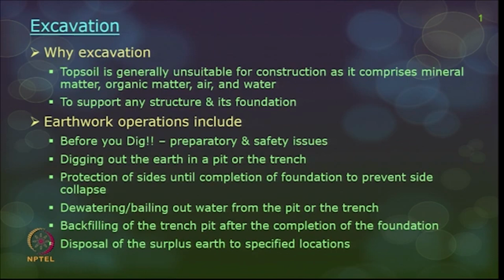Now why should you go for excavation? The top soil as such is not suitable for construction, and it comprises mineral matter, organic matter, water, air, etc. That's why it's not really suitable for construction, and hence the soil has to be removed. I am talking about surface excavation, and deep excavation also generally happens to support a structure and its foundation. Even the top soil has to be fully leveled and cleared, and separate holes or openings have to be made, earth has to be cut to support the structure and its foundation.